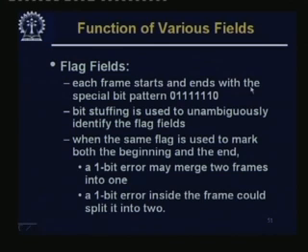Each frame starts and ends with the special bit pattern. How do you know that for the framing purpose? So, this is a special pattern which is used for start and end. Of course, if you use a special pattern, in order to accommodate this pattern within the data itself, you have to do bit stuffing, which is used to unambiguously identify the flag fields.